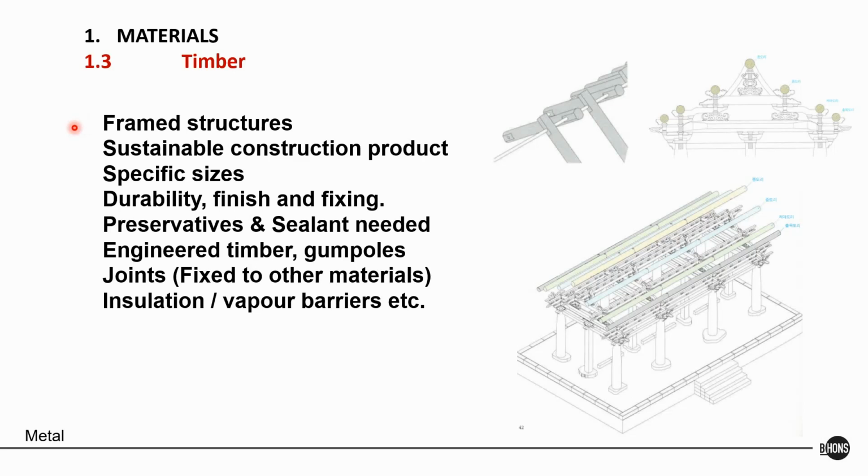Dry conditions and high UV are quite damaging for timber and need to be dealt with appropriately. So we often find timber structures more in humid conditions where it's not as rough, and a little bit more overcast. Something to think about whenever you're designing in very harsh conditions, as we would find in the South African interior.